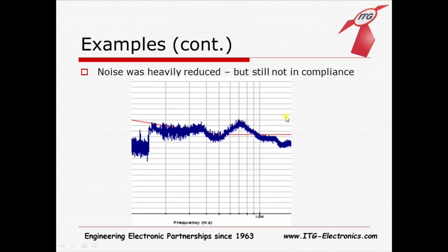And then after this is a very zoomed in section of the resulting noise profile. Everything outside of this zoom is within the spec's limit. It's below the red line, but we still have some areas right in here that are concerning. Even up here, as it's below the line, it's very close. So we typically want to have at least 5 dB kind of safety net below the line to make sure that everything is going to be well in compliance. But everything above the line is obviously a problem.